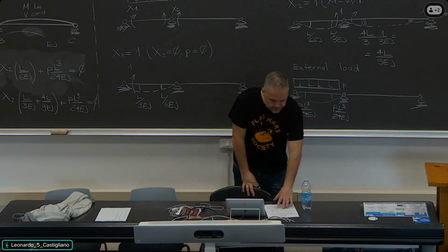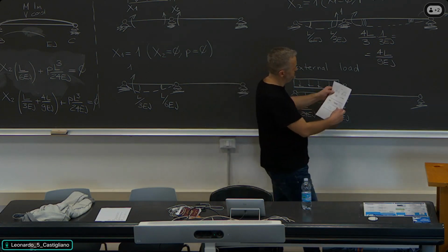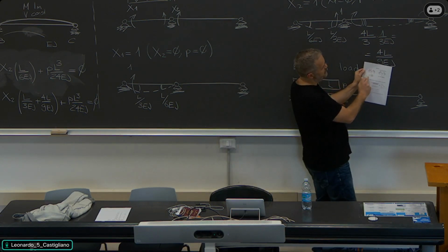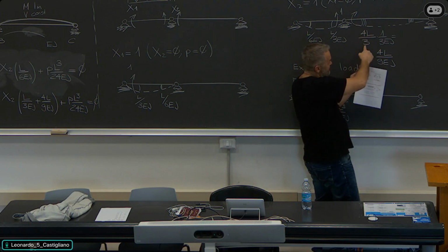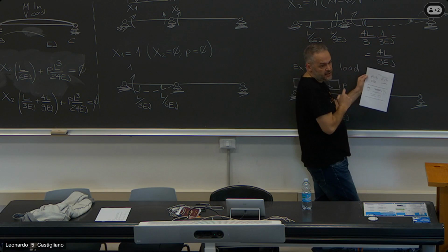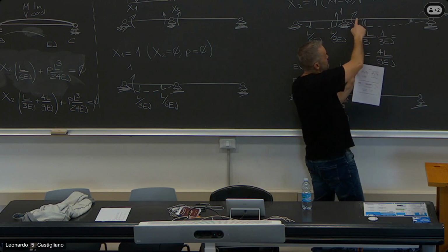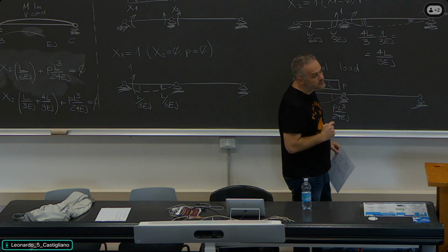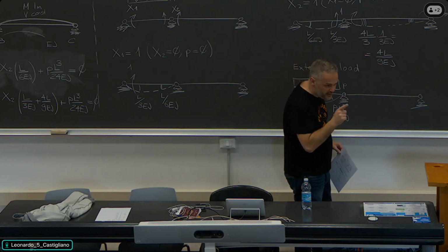No. First coefficient tells you that in the standard case, at the point where the bending moment acts, the rotation is L over 3 EJ. Replace L with 4L divided by 3, 4L divided by 3 divided by 3 EJ at the loaded end where the bending moment is. So I just have to focus if it's on the left or the opposite?